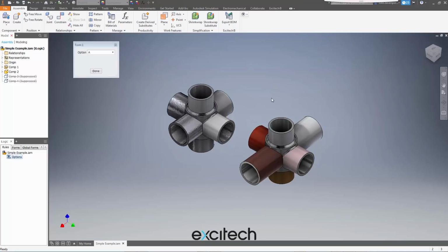So this method of placing all the possible components you'll need in the assembly traditionally created a bit of a glass ceiling in iLogic in terms of how much flexibility you could feasibly build into your iLogic assemblies, because adding more options meant exponentially adding more and more controls in your iLogic form and exponentially more code for each extra component and option you add. And also, you had to use a custom level of detail in order to suppress the unwanted components, and that could lead to some frustrations also.